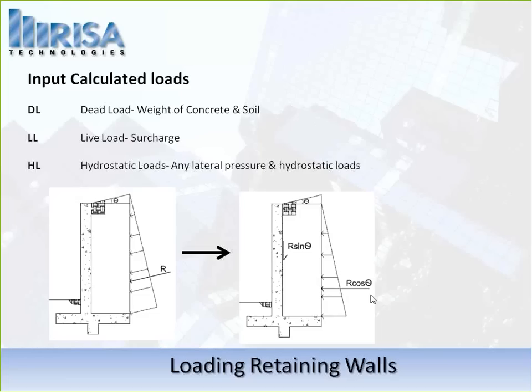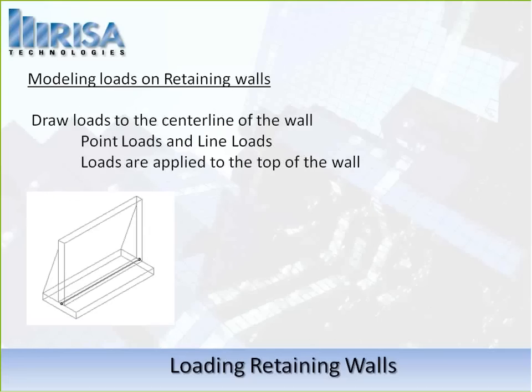The other thing that we will talk about here is some of the modeling that we're going to be doing. When we model these loads, we're going to want to model them directly on the wall center line. Now this is important to note, since this is three-dimensional. In RISAFoundation, we're typically looking at more two-dimensional. This retaining wall is our first time where we're really in three dimensions. So we've got to see that this gray line here is what we call the center line of the wall, which is really the base of the wall. And when we apply loads to that, we're applying them along the base there.